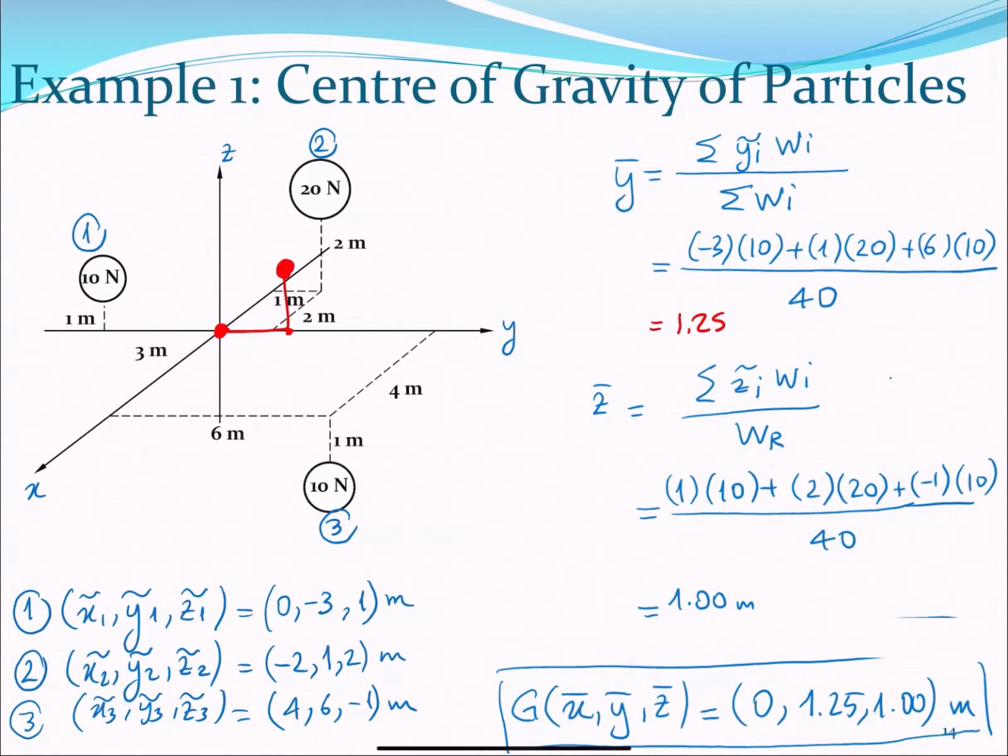So at this point, I can replace the 3 loads by the resultant load, and I will cause the same moments as this rigid body in any direction, right? I can just place WR through that point, and it is the same as having that 3-particle body. And for the purposes of calculations, this will make things quite straightforward.